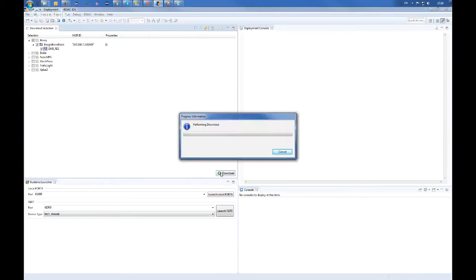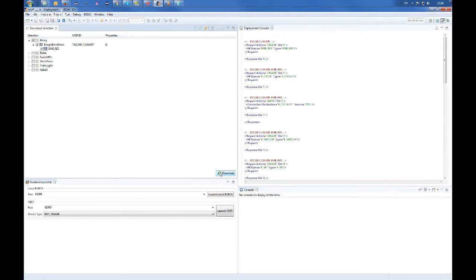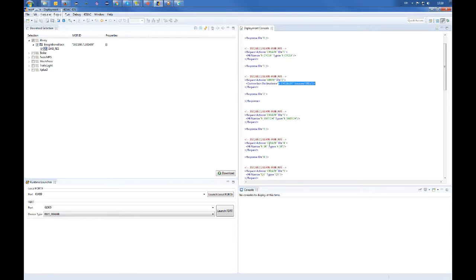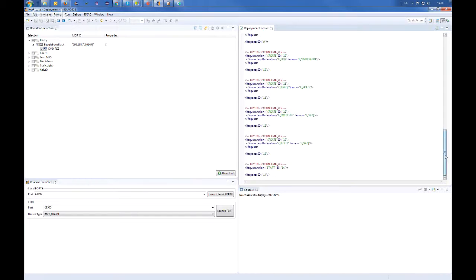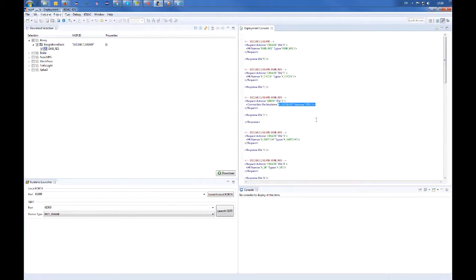And by pressing the download button, perfect, 4diac is sending a set of configuration commands down to the PLC device, or in our case, the BeagleBone Black. And these are commands like create me an instance of the eCycle, write the parameter 1 millisecond, create connections between them. And this is what I meant before when I said we can now change it. So you can send the next command like adding a new function block, removing a function block, changing a connection. And this is the great power of this modeling language and how we implement it in 4diac.